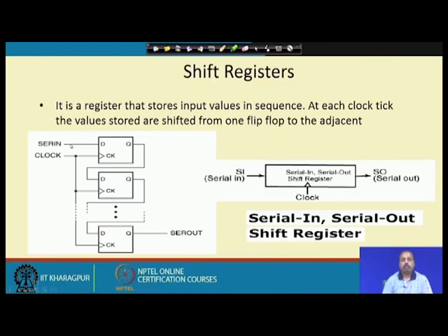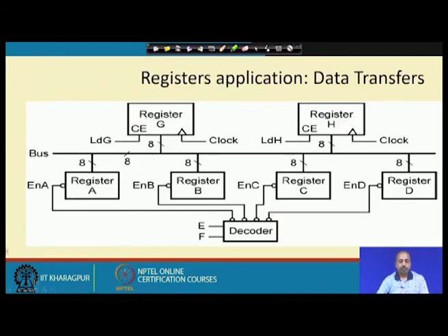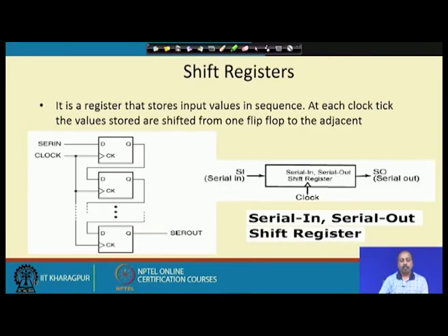The problem with this previous structure is that if you are trying to store some value onto these registers, I have to give 8 bit parallel lines, but often getting so many parallel lines from somewhere is difficult. So, we want to transfer the data serially. So, this may be a higher size register, maybe 8 bit register or 16 bit register, whatever, but I am not feeding all those registers simultaneously with external data inputs. They are coming through this serial input line.